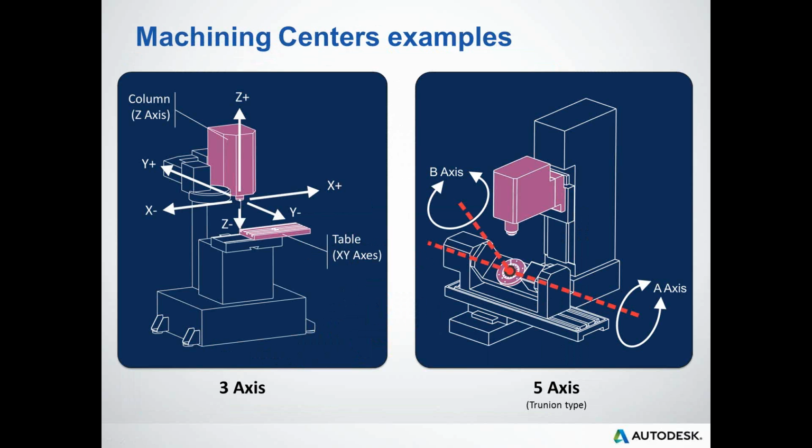Then we have 5-axis machines, basically adding a rotational or index to the picture. Indexing can be done in 90-degree, 45-degree increments, but on the rotational side of it, sometimes we run into machines where the rotational axis doesn't just index to a specific position, it can actually feed as it's indexing. And that gets us into 4th and 5th axis simultaneous, or perhaps X, Y, Z and A and B are moving at the same time in a feed environment.